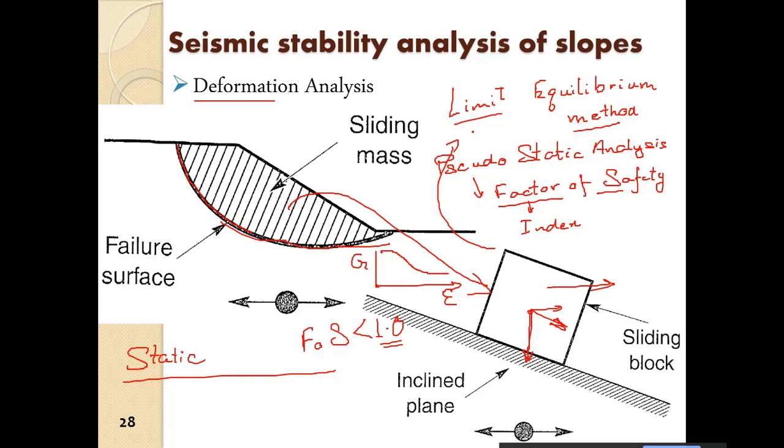All right, so deformation of the slope is also important, as far as the serviceability. We have seen that if there is a significant amount of deformation in the slope, it may lead to cracks and fissures in the slope, and water will seep in, and what will follow is catastrophic failure. So we need to assess every possible angle and converge into a solution. That is the slope stability analysis.